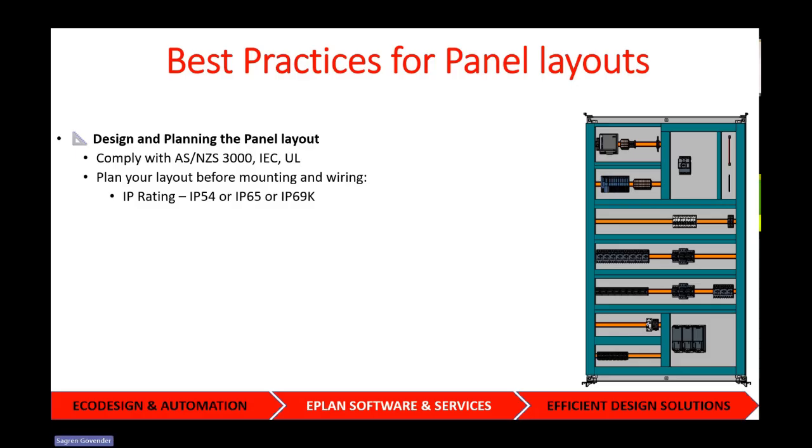Of course, it starts by knowing where your enclosure is located. Is it located indoors? Is it located outdoors? Is it located in a food hygiene area? And that helps you to select the correct IP rating for this enclosure.